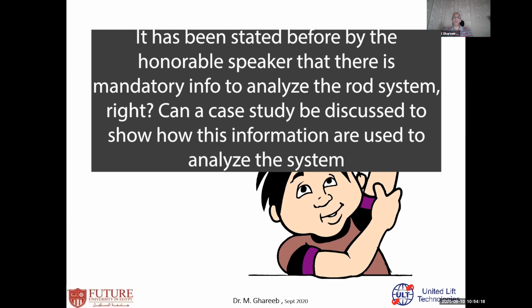If you look at one of the slides I mentioned, there is a lot of information you need to have, but as mandatory information: well inflow performance, fluid properties, my downhole configurations, what pump I have, what pump size I have, what the metallurgy of the pump is. Maybe I have a downhole pump that is just carbon steel, and I run this pump in a corrosive environment. I did my analysis, I say the traveling valve has some problem.